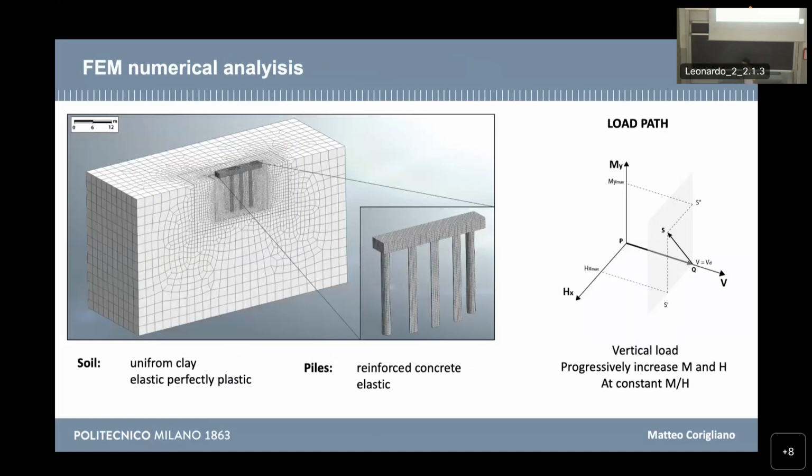And then let's pass to the more sophisticated approach, that is pseudostatic finite element numerical analysis on one half of the foundation, thanks to the symmetry, in which the soil is an elastic, perfectly plastic medium, and the piles are modeled as elastic.